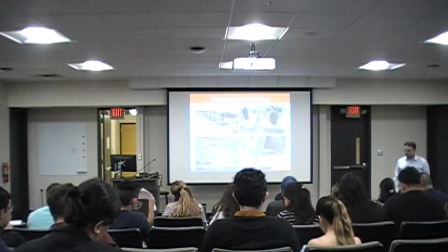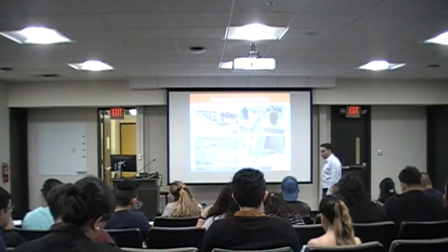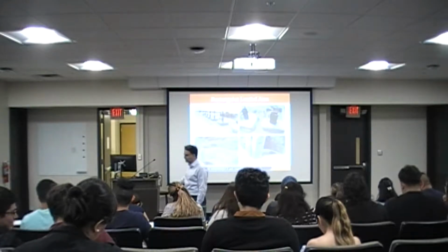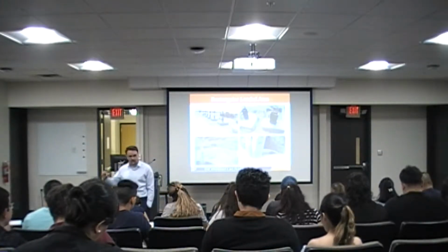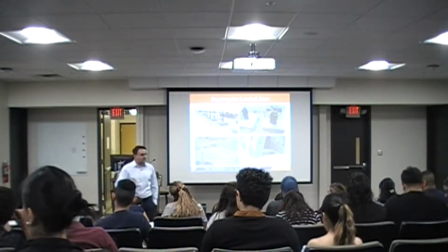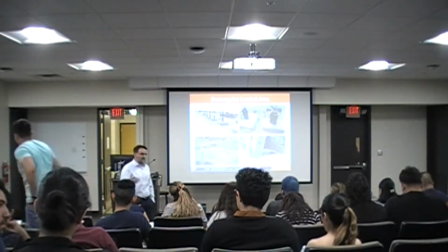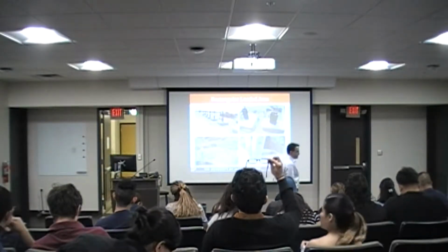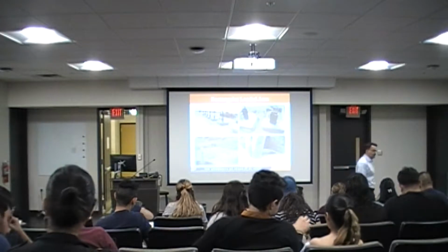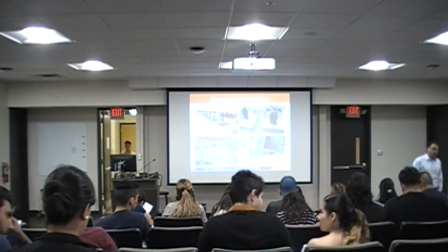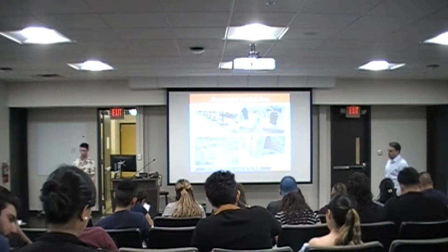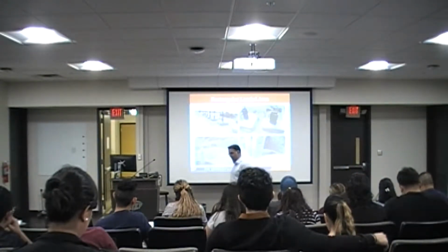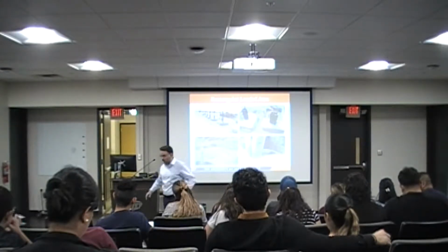So we have external loads, and we know that initially there are some stresses in the soil. We call those geostatic stresses. Those are the initial stresses. And then you apply the load and you have a stress increase. Remember, we call that the delta sigma concept. And we have different ways to be able to calculate that delta sigma. Remember, we talked about the Boussinesq theory, Westergaard theory, Newmark method, and ultimately the 2-to-1 method, or assuming that the distribution of the stresses happens at 60-degree angle.